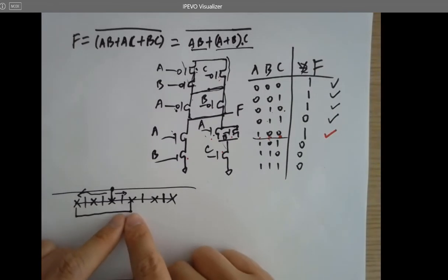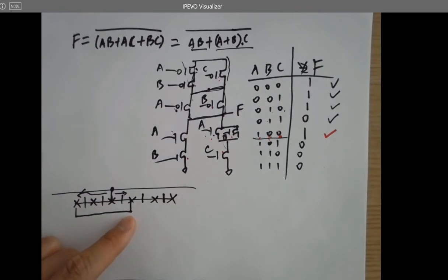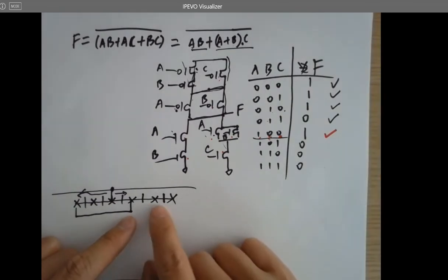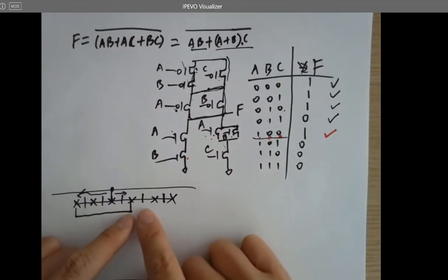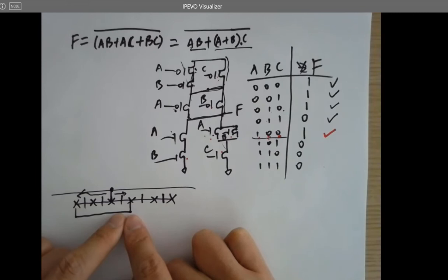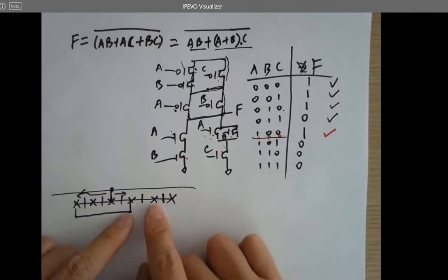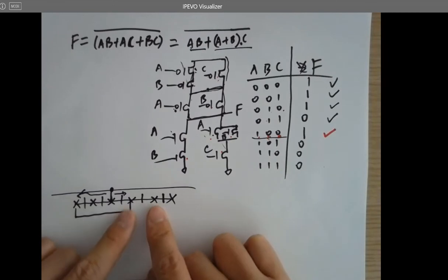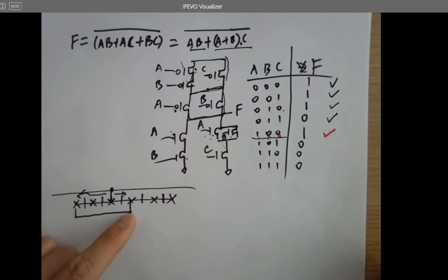Since all the metals are supposed to be connected metals, right? Or P plus terminals. These terminals have vias. You don't want to connect this to the gates. It's not what you're supposed to do. So there are only 2 terminals, right? You have to make some connection from here. And there are just 2 terminals available. Just try one by one. And if you try here, then it's shorting these 2 P pluses for this PMOS. It definitely won't work. So what you want to do is actually short it to here. That's the only way you can make this connection.